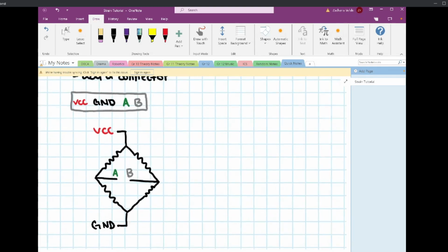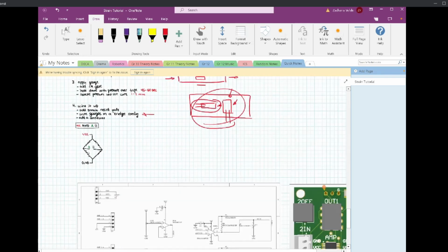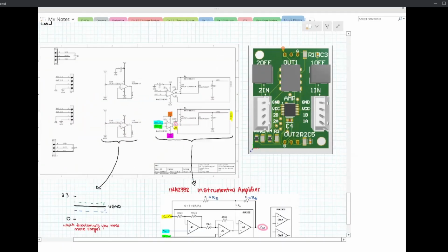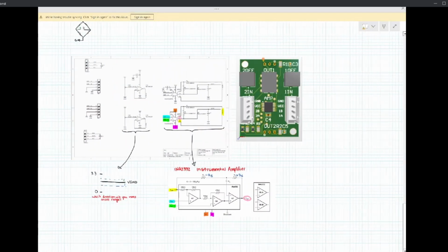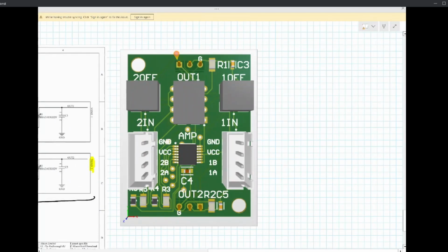But yeah, this is the exact configuration. Usually they're not really plus and minus, they're just two analog outs. They act as two analog outs, and this is what we send back to the PCB that has a Wheatstone bridge on it, which brings me to the PCB. So this is the current revision that we're working with, and this is the revision that will be used for the tie rod and the camber links and maybe the steering column.